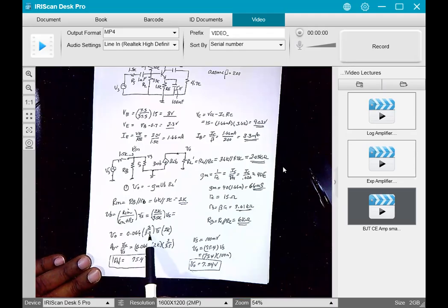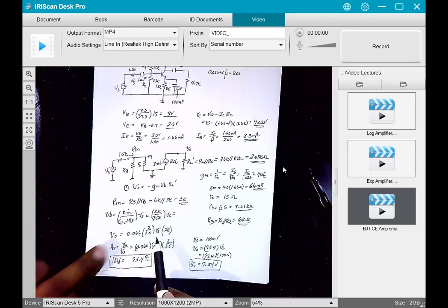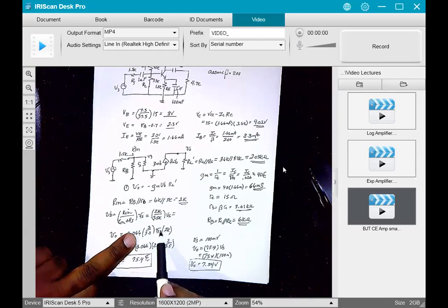Millisiemens. And then you put the 0.06. Okay, all right. We good so far? Yeah. So that's where, and then here's the voltage divider, RN over RN plus RS times VS. So all of this right here is VB. I just substituted this expression right here.